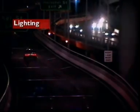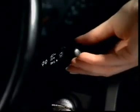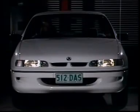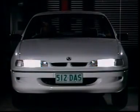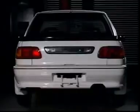This section examines lighting. Lighting systems improve visibility at night and make a vehicle visible to other road users. A lighting switch operates tail lights and park lights and headlights to allow the driver to see ahead. A dip switch allows the driver to change the beams from high to low, or vice versa as required. Stop lights operate when the brake pedal is depressed.